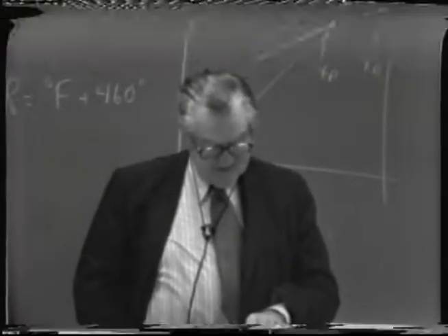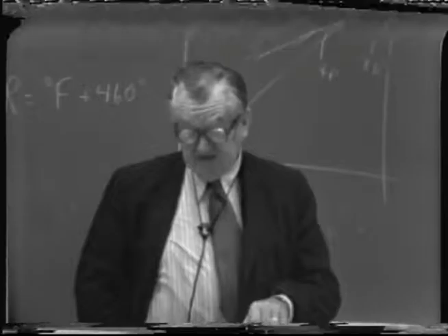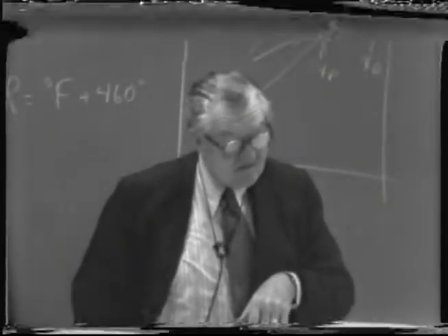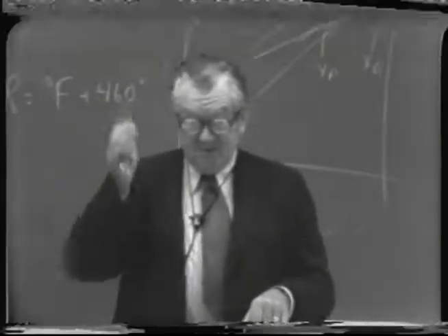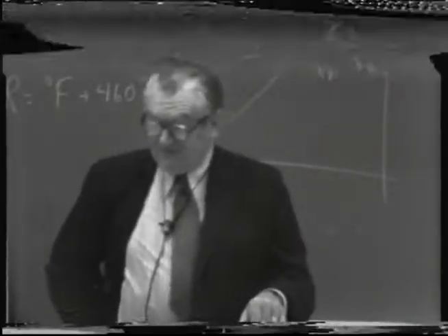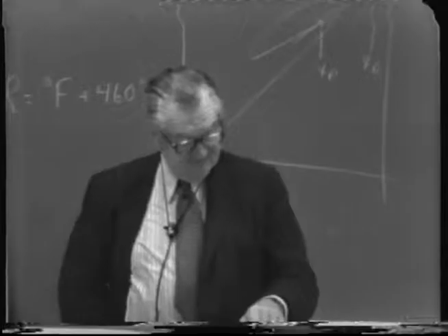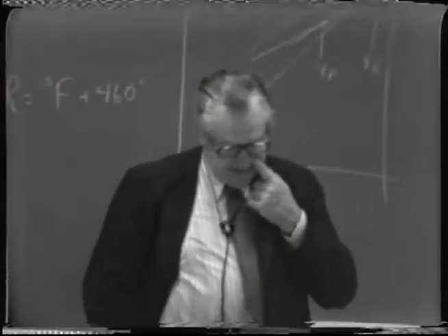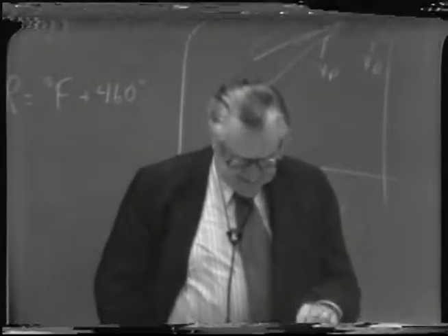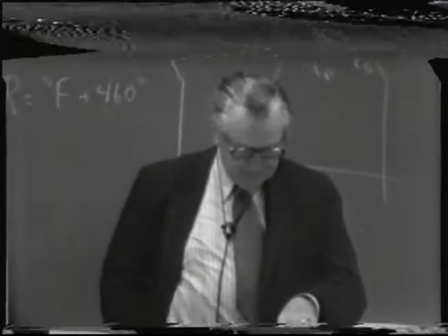And this is particularly the case where you have very low alcohol feeds like this and have an appreciable requirement of heating the feed up to the boiling point, from 140 up to over 200. So the vapor rate then comes out to be around 1,396 according to these figures here, moles per hour.